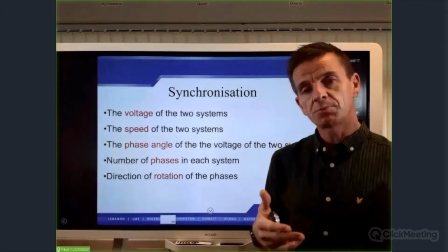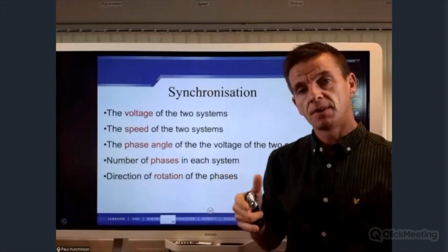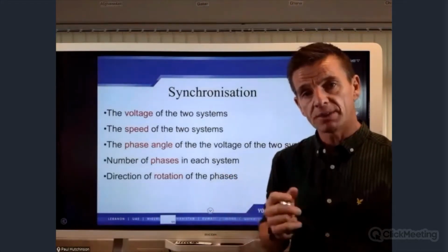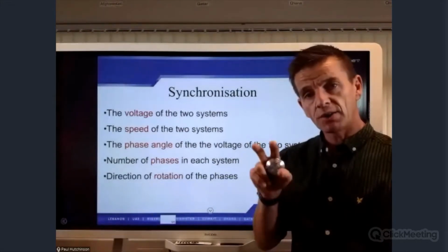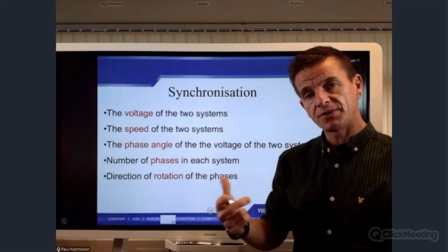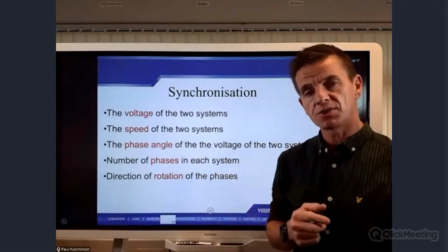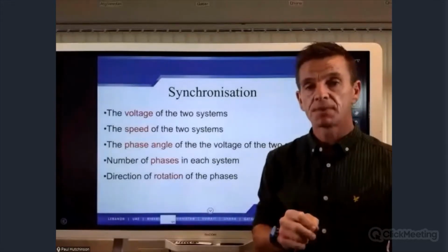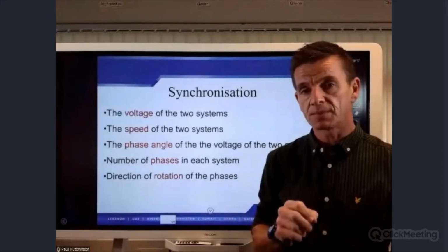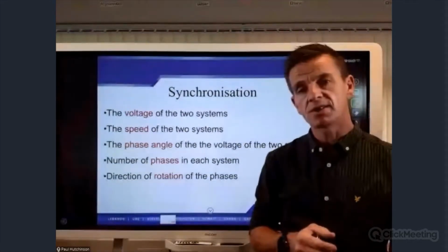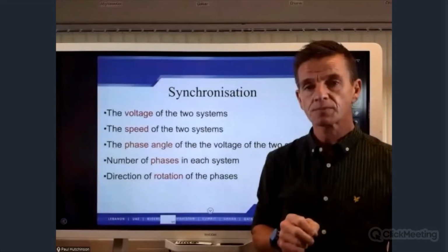Okay. Again, as part of your checks, you would use a calibrated meter, normally something like a Fluke meter, and you would check the output of each of the alternators and other source that you're synchronizing to ensure that the voltage is identical. Okay, so you should be reading the same voltage on all gensets as what you're synchronizing to on your source.